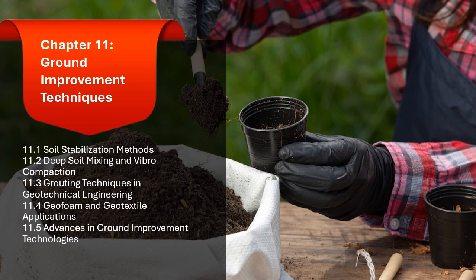1.3.3.4 Seismic hazard mitigation. Grouting can be used to mitigate the risk of liquefaction during earthquakes by increasing soil density and reducing permeability. Grouting helps prevent soil failure and ground deformation under seismic loading. This is particularly useful in loose sands or silty soils that are prone to liquefaction.